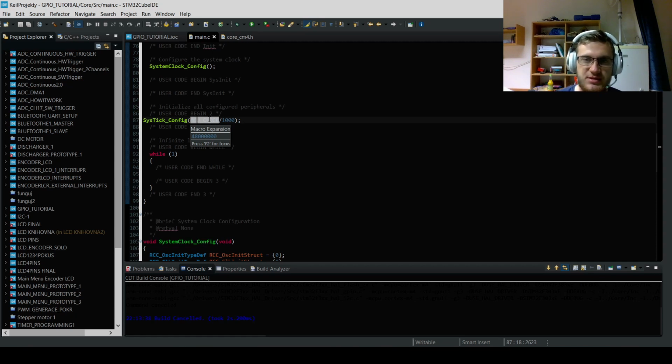And the period is 1 microsecond. So every 1 microsecond, the SysTick timer, which is directly connected to the internal oscillator, the internal clock, that's as accurate as it can be, will throw an interrupt. The thing is, for now, I will leave it like that, it will throw the interrupt the entire time. Even though we are not using the delay, the SysTick timer will still interrupt, but it's okay.